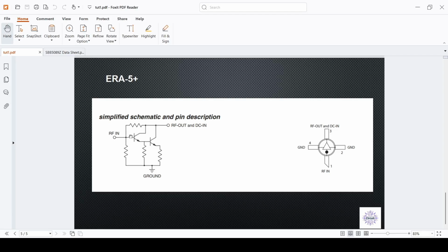One of the ways is that when we look at the input of this amplifier, we need to see 50 ohm across all the frequencies. That's why they put everything inside the integrated circuit. The parasitics of these resistors are much less compared to when they want to add them outside of the IC, right? That is why, when they put these resistors inside the IC, because of low parasitics, they can offer the amplifier from 50 megahertz to 6 gigahertz, right?